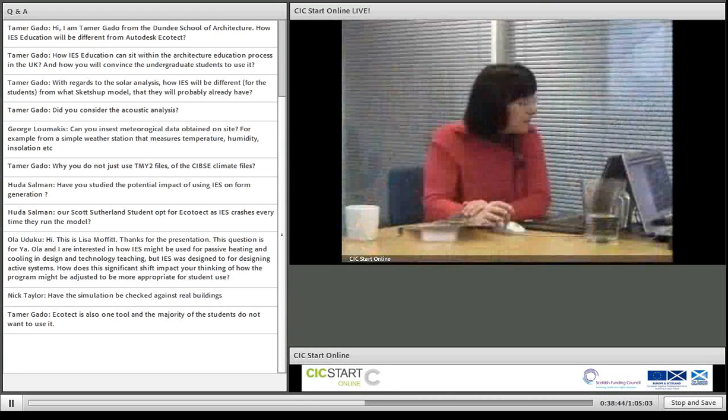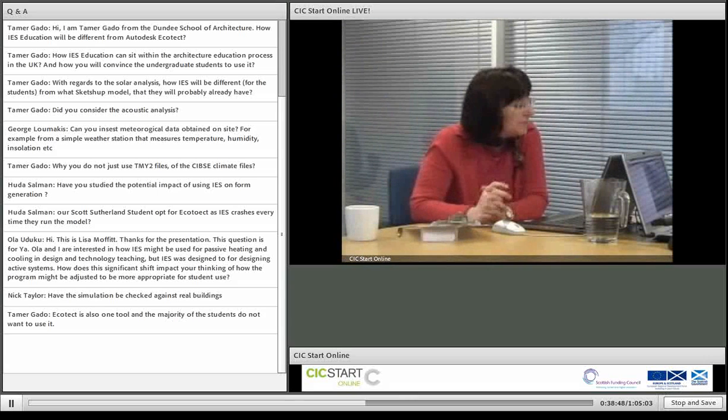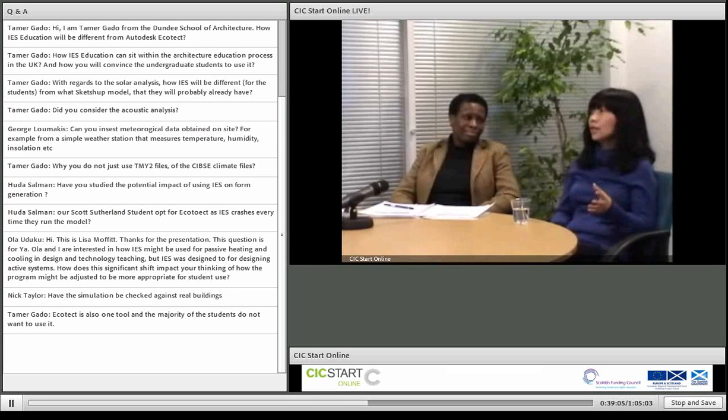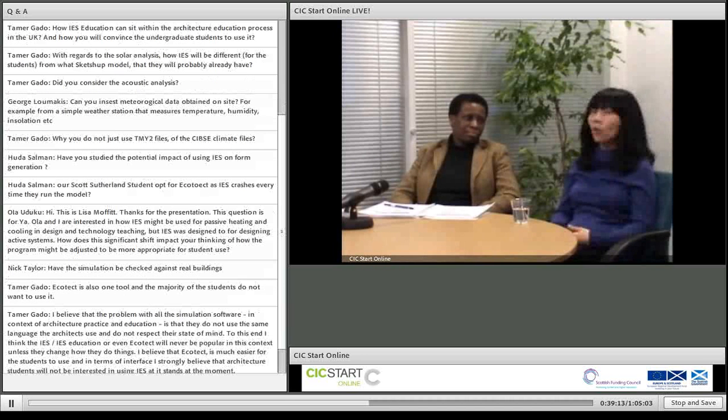A question from George Alumakis. Can you insert meteorological data obtained on site, for example, from a simple weather station that measures temperature, humidity, insolation, etc.? Yes, you can. The standard weather file is based on hourly data, but if users have their own measured weather data, perhaps half-hourly, you can import your own climate.